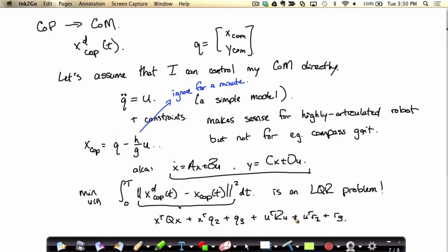My apologies. All right, so this is a big deal. This tells me that if I have a center of mass and some trajectory, I didn't actually derive it, but it's in the notes, it turns out you can solve LQR even if you have these other terms sticking around in there too, okay? This thing is often called the linear quadratic tracking problem. But it's right in the LQR notes chapter, and it's just a minor extension where you have these extra terms to cancel, but the Riccati equation idea still works, okay?